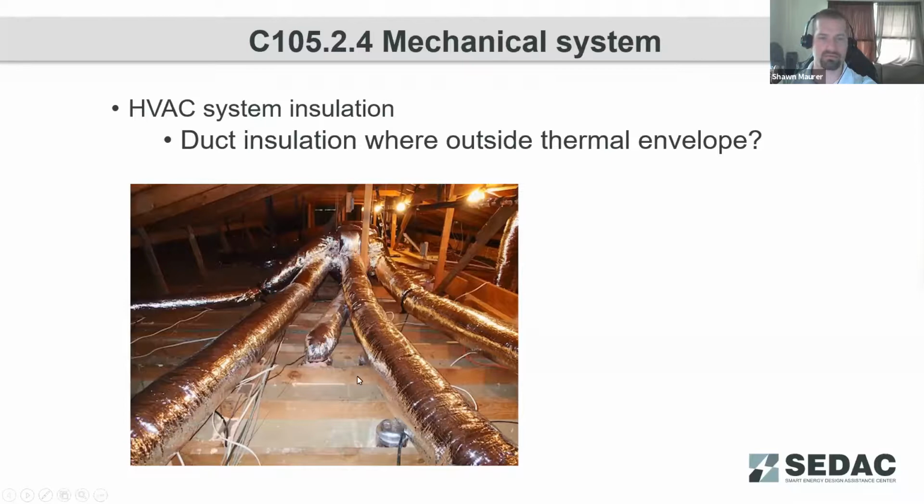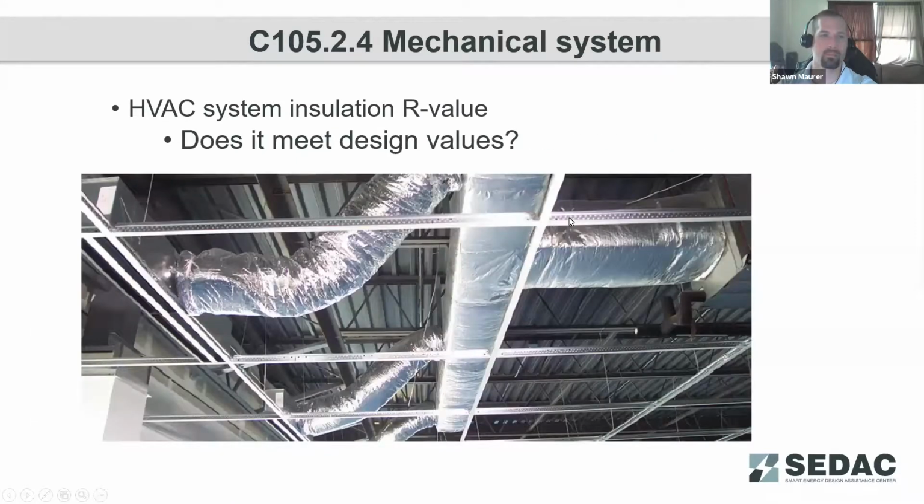And so again, as the code official is going through the building, he's going to be looking for proper duct sealing, making sure that joints are properly masticed or taped, that those mastics or tapes are UL 181 rated, so that they're going to provide that lasting seal in the duct system. For duct insulation values, does that meet the right design?